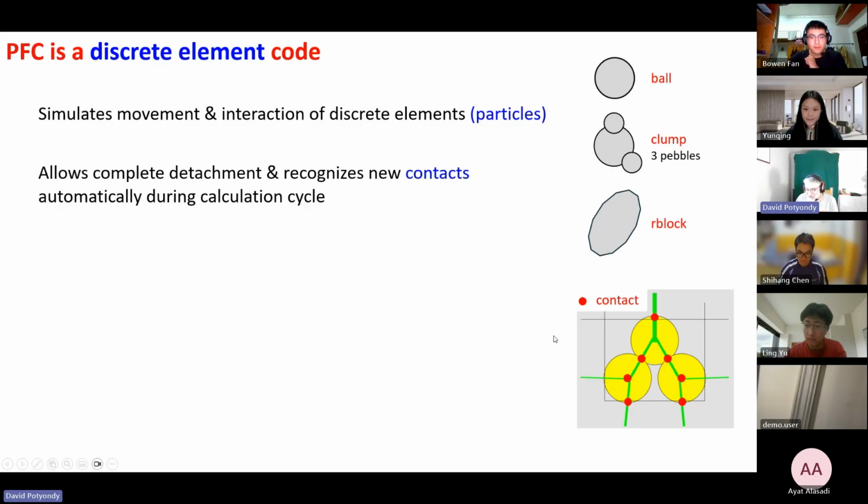And you also are seeing here the forces flowing through the system. This green is the force at the contact. The thickness of these lines is related to the magnitude of the force. And so you're seeing how this is being pushed on the top, but then it's pushing on the side. That makes this guy be in equilibrium. It's pushing those guys out, right?